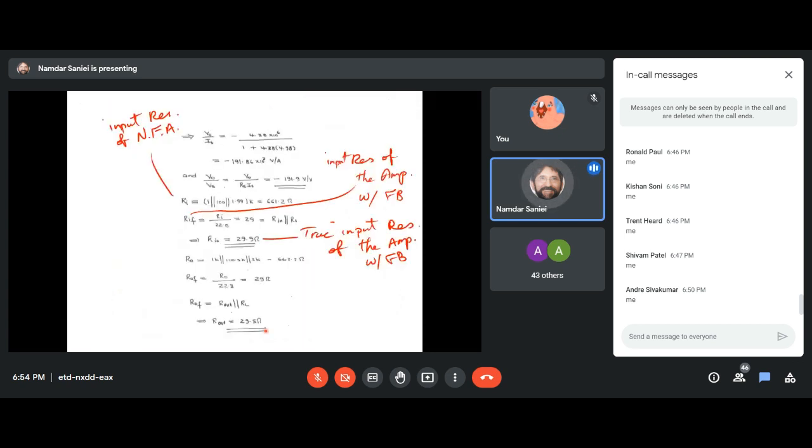Now, if we look for the gain with feedback, AF, it's going to be A over 1 plus A beta. And this is what we get. But if we have VO over IS and were interested in VO over VS, it would be sufficient to multiply that trans resistance gain by RS in the denominator. Okay, and this would be the voltage gain of the circuit.